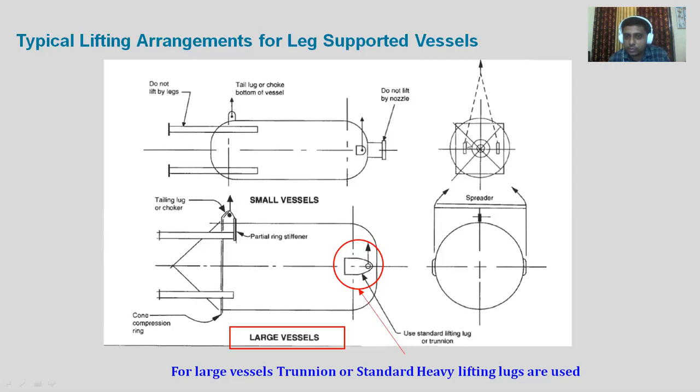That vertical force will be resisted by this entire width of the lifting lug. But there will be one horizontal force coming, right? Because of this horizontal force, it will be bent across its thickness. So thickness is not much. So its section modulus along the thickness is called a weak section modulus, or we can say one is a strong axis, another is a weak axis.